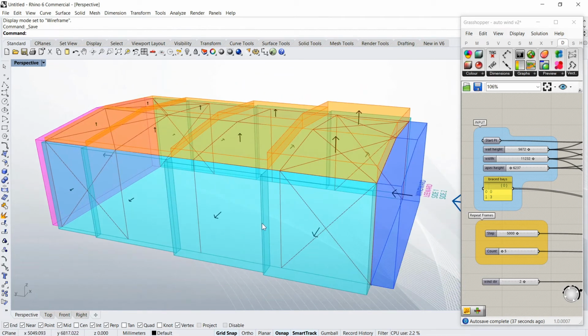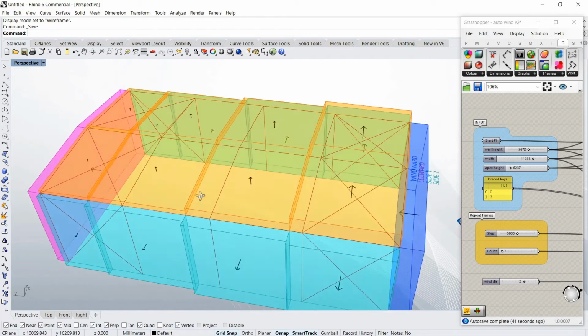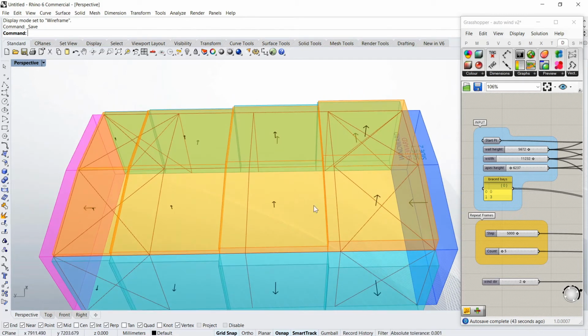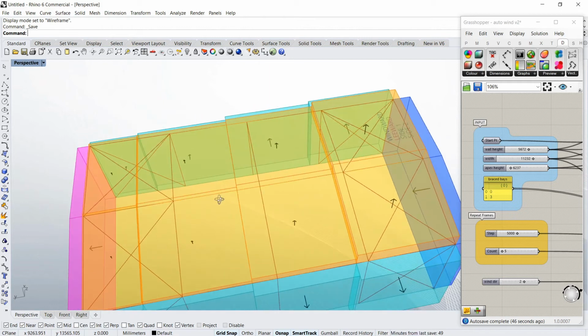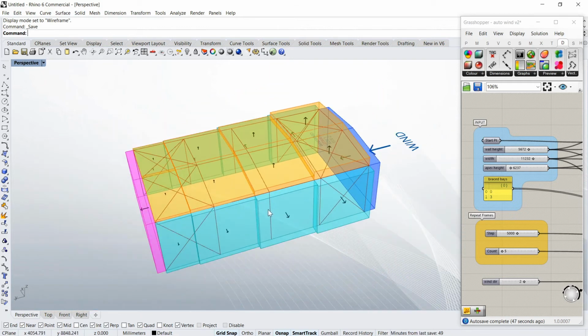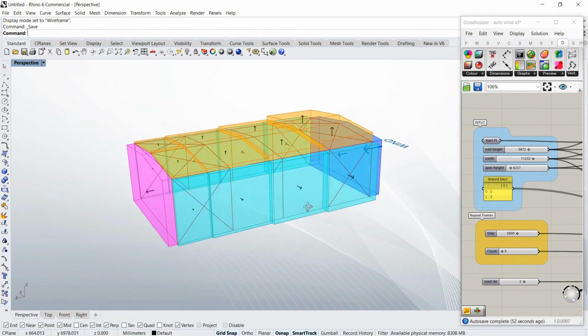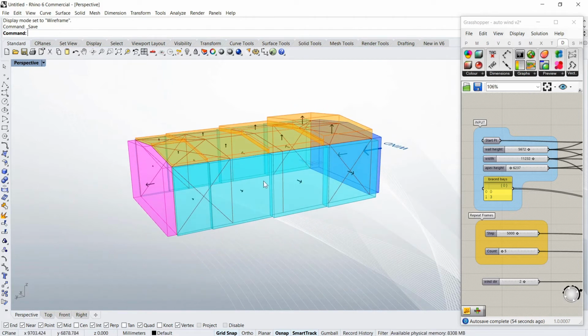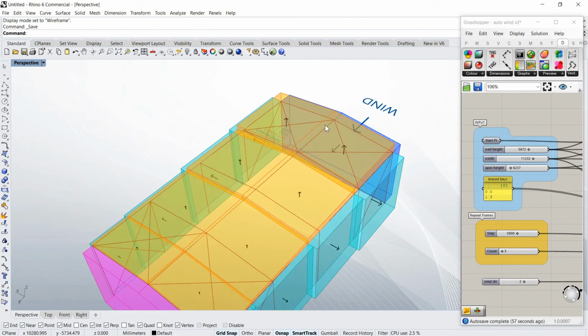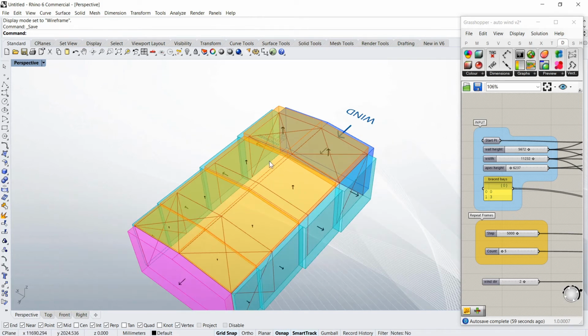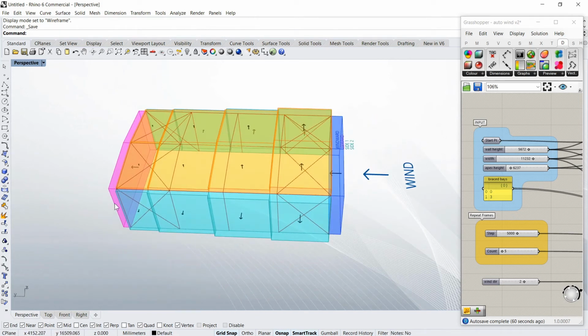And in the next step, I'm going to use vertically spanning cladding on the walls, and I'm going to span the roof in the Y direction. But bear in mind that the cladding on the walls could span horizontally as well, and the roof could even span the other way as well, although that's not common.